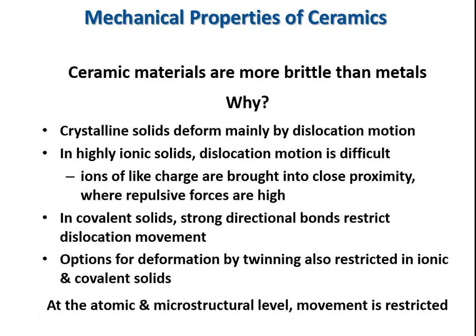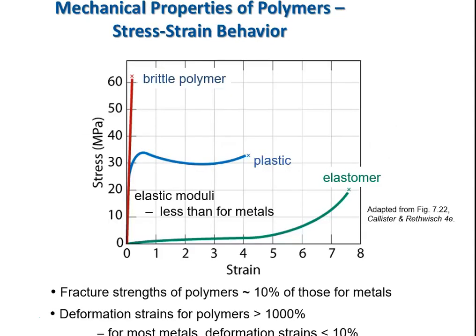So again, the more at the atomic and microstructural level you are restricting movement, the less likely you can get plastic deformation, the less ductile, the less fracture tough. So there's ceramics in a nutshell, why they're brittle.